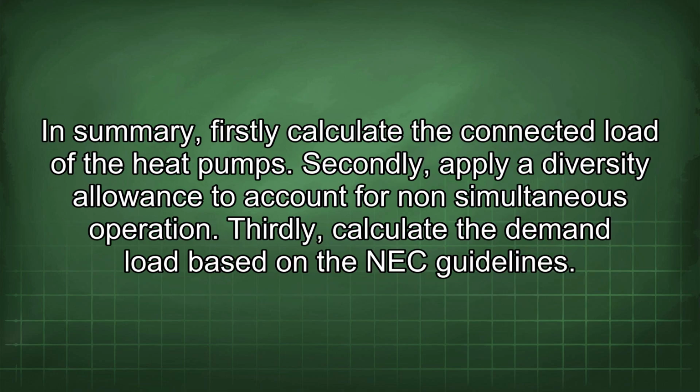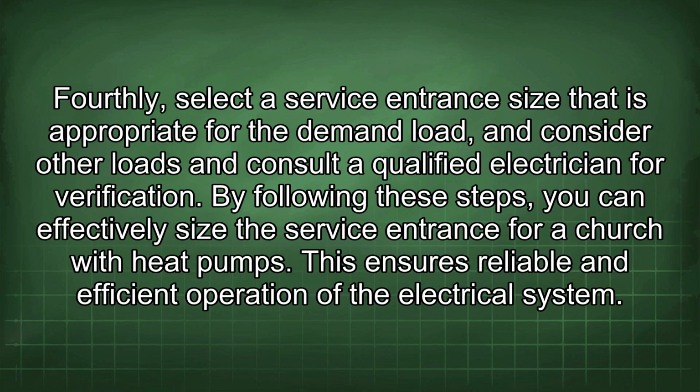In summary, firstly, calculate the connected load of the heat pumps. Secondly, apply a diversity allowance to account for non-simultaneous operation. Thirdly, calculate the demand load based on the NEC guidelines. Fourthly, select a service entrance size that is appropriate for the demand load, and consider other loads and consult a qualified electrician for verification. By following these steps, you can effectively size the service entrance for a church with heat pumps. This ensures reliable and efficient operation of the electrical system.